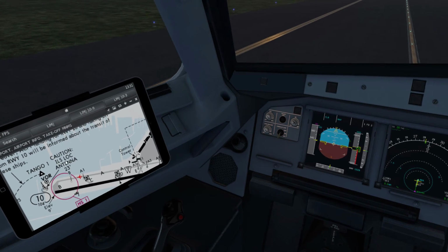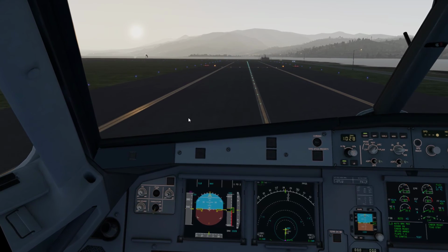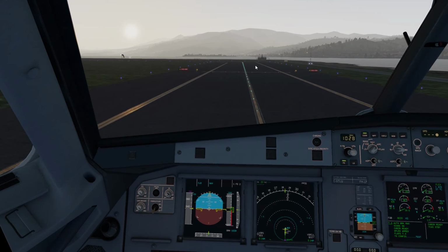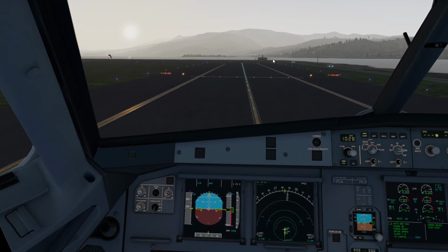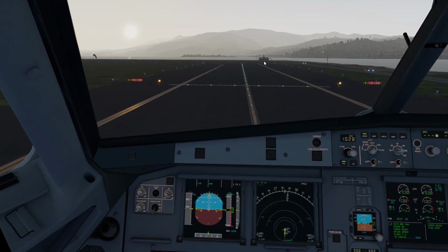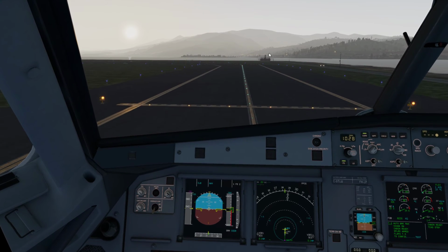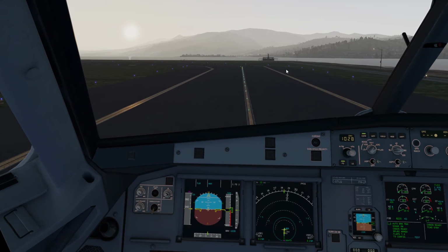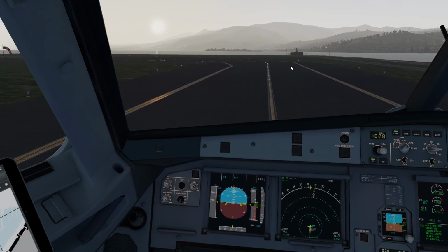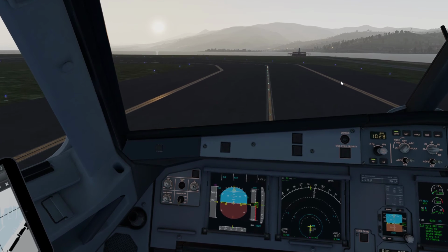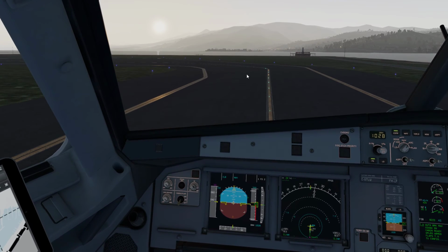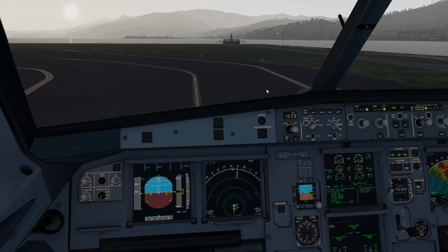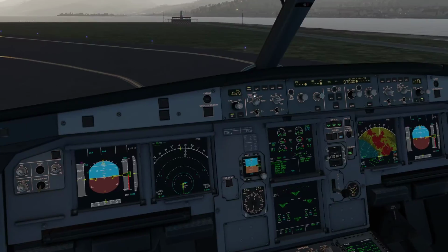So, caution ILS lock antenna. Typically I think you have to stop here in order to not block the ILS antenna. I already heard of incidents where planes actually crashed because the ILS system was blocked, and when landing you need that. You really need that. If it's blocked, the ILS will just throw you off the runway or something, like just lead you somewhere wrong. So you never want to block that.